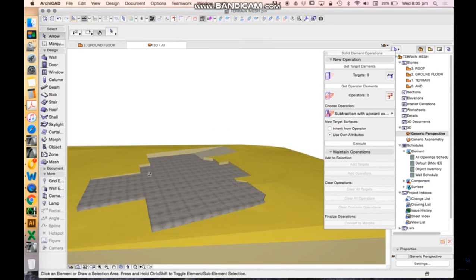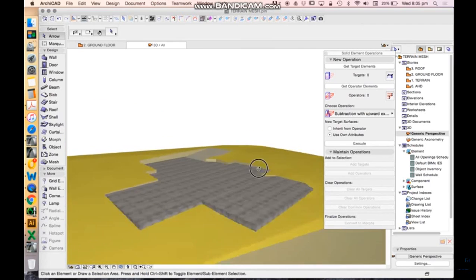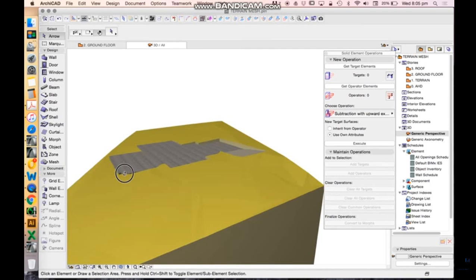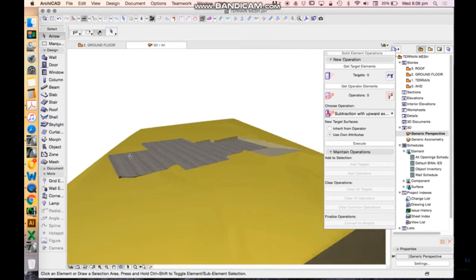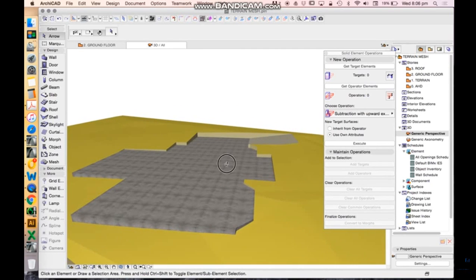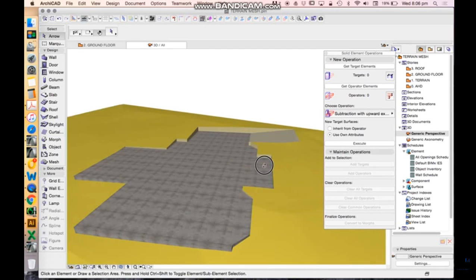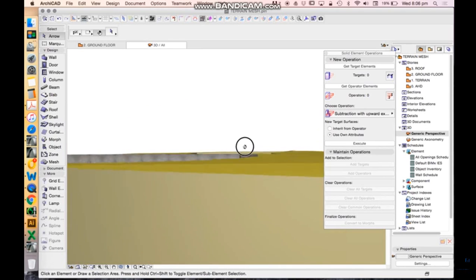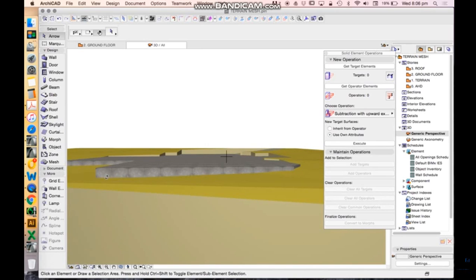So we can use this for construction or for landscaping, and it's a very good visual representation of how our building will fit on the site. So if we go to the effort of drawing the terrain mesh properly, it's going to give us really good interactive feedback as to how you should be positioning your building on site. Of course, the reason for this is that if I was trying to get this building to be flat on site, we'd see that we'd need to fill it over here a bit.